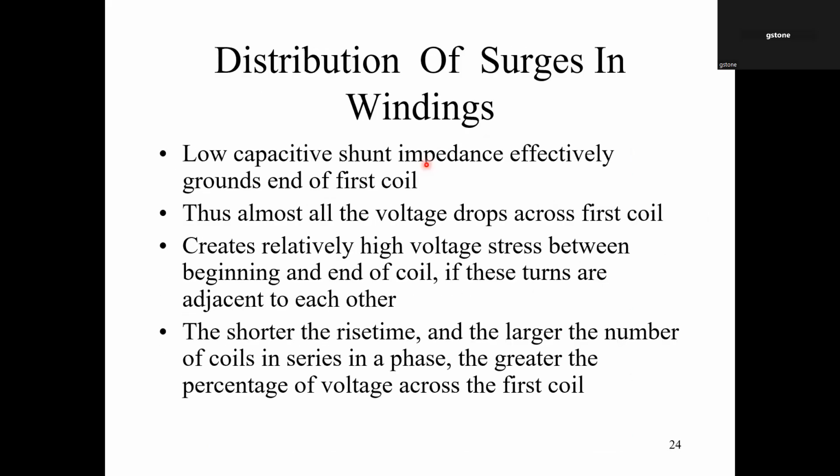And this is where it causes problems. Okay, so this is because of the capacitive effects and the fact that current always wants to go through the path of least resistance, which happens to be, when you're dealing with 3 megahertz, through the capacitance to ground. Then what happens is almost all the voltage is dropped across the first turn of the first coil.